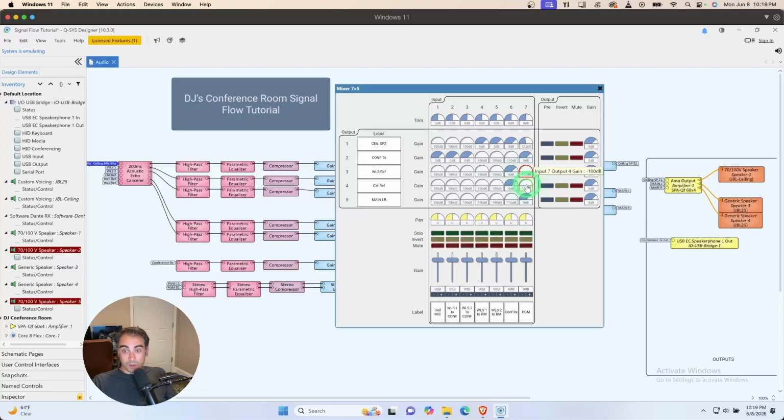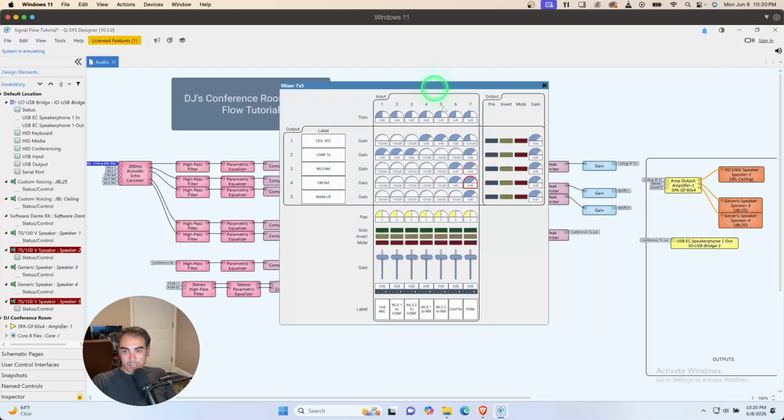And we definitely want our program audio to go to the reference, because that is audio that's coming out of our speakers that we want to be canceled out going to the far end. So we want to send the direct signal and not be hearing echoes of program audio. So that is our basic routing inside a Matrix.